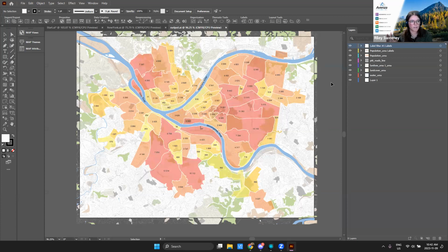And there we go. There is definitely some excess data hanging off the edge of the artboard. That's just based on the buffer size that I gave to that clipper object. So I could tweak that, or I could just crop from within here. We've still cut down those data sets significantly, so the crop's not going to take as long. But yeah, using that workspace, you can automate a pretty complex workflow, and you can end up in a really great spot to come into Illustrator to do your final details.